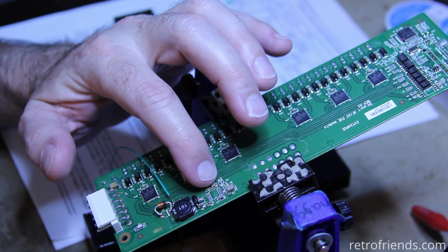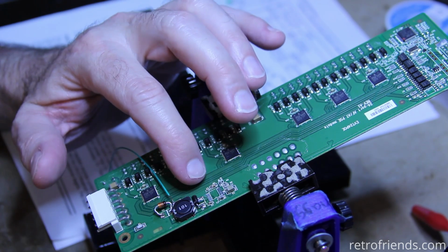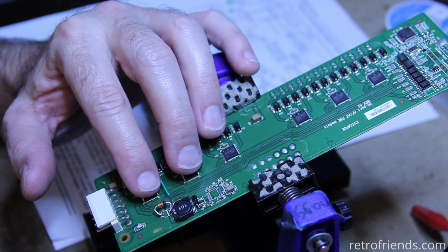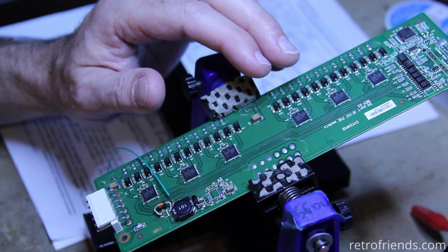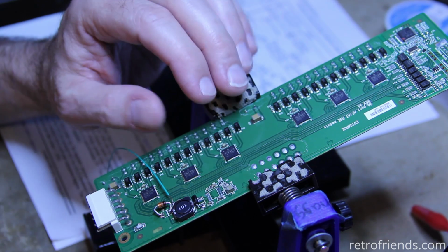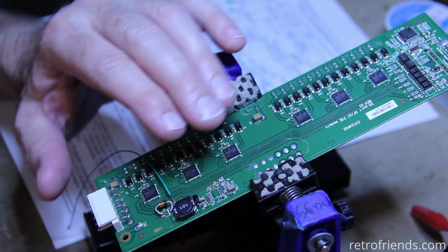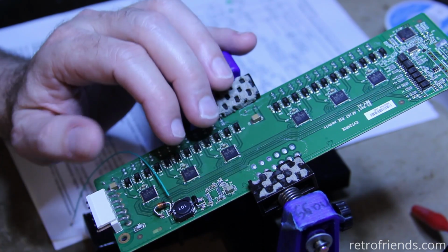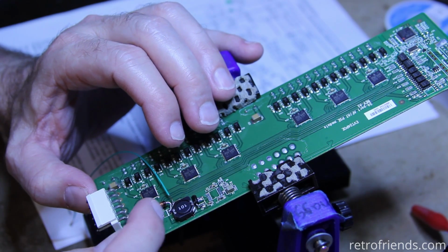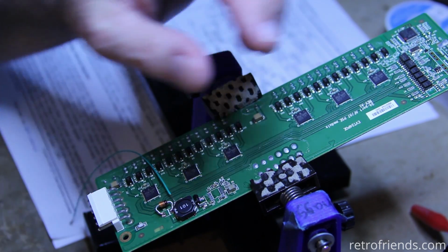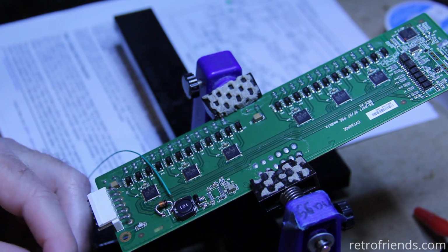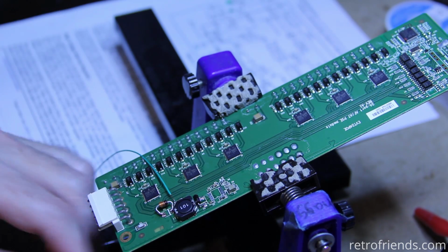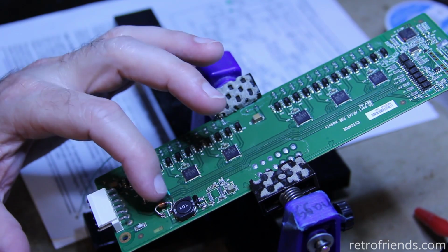So with that part removed, obviously it only leaves passive components. I guess one of these controller chips could be partially shorted or otherwise pulling too much power. And I noticed that this whole corner of the board is getting warm, this whole area right here. I narrowed it down to this inductor and this diode, which was an SMD diode. You could see I replaced it. But there was an SMD diode there, here and here, and I didn't have SMD diodes. This one's a Schottky, and this one is a Zener.